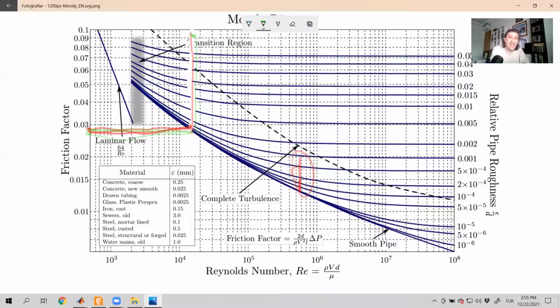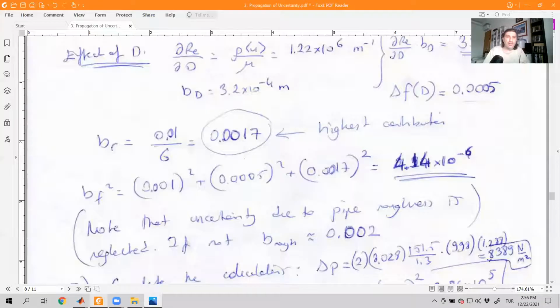Note that this is a logarithmic scale, so it's not going to be very easy to make an accurate reading between 0.2 and 0.3 using a regular ruler. So I'm not very comfortable with that 0.01 resolution. I think this should have been slightly lower, maybe 0.05, something like this.